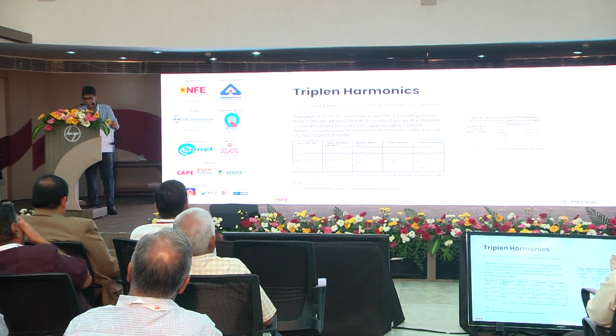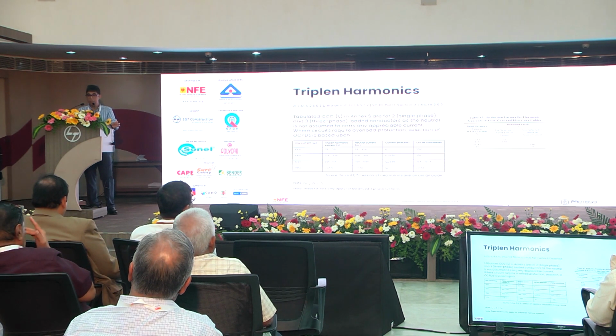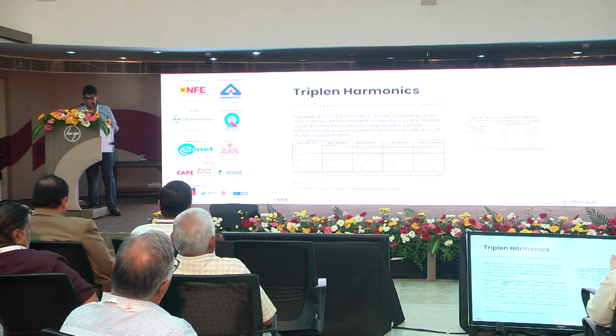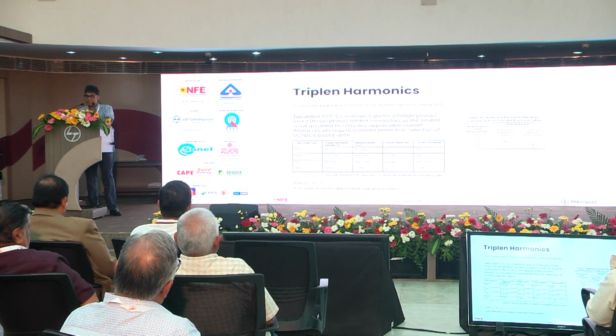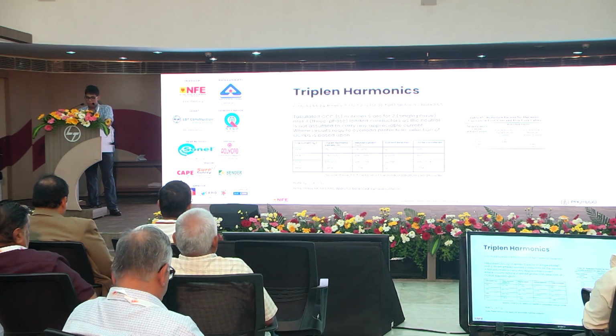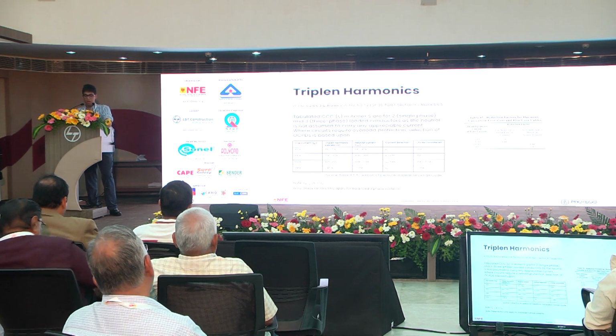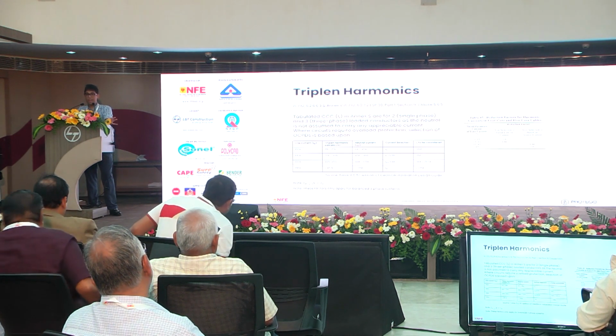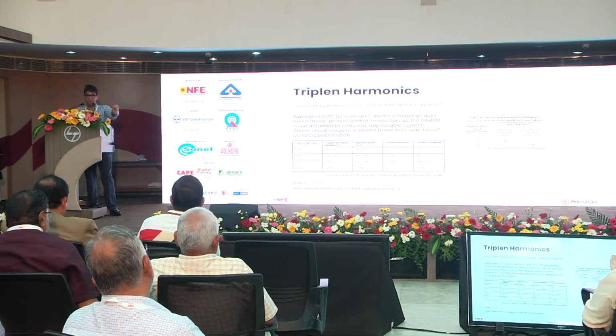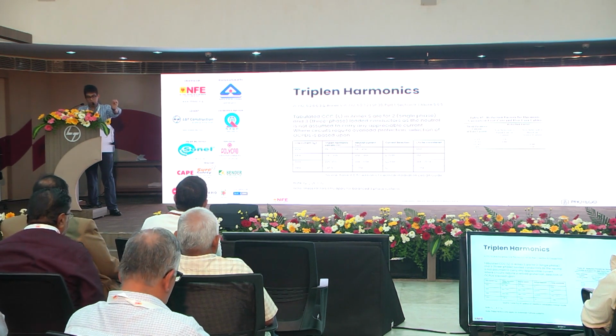All you do is take the line current and derate by 0.86, so 116 amps. Now, the neutral is going to carry 116 amps, where your line conductors are carrying 100 amps. So then you need to choose a cable rated for 116 amps. When you start seeing triplen harmonic distortion over 33%, then you can no longer base your current carrying capacity on the line conductor. The Iz value that we choose has to be based on the neutral conductor load.